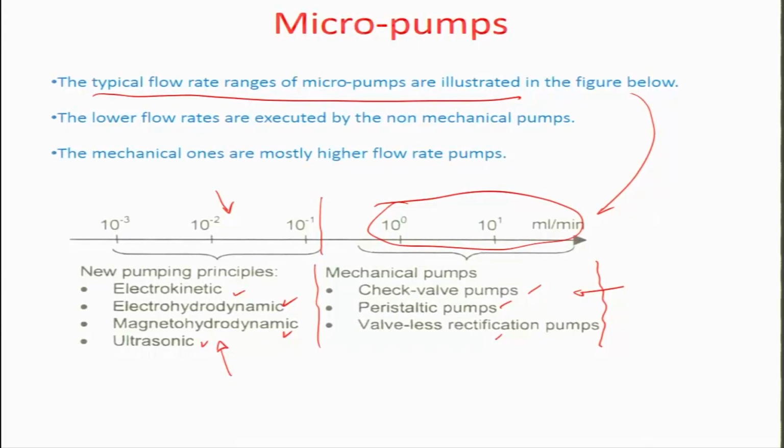But then what is the reason why such new pumping principles and such innovative actuation schemes are initiated? One of the major reasons is that in microfluidic flows, particularly when we are talking about applying these to human diagnostics, clinical diagnostics, etc., the volume is very low, and you have to have a very controlled motion of a very small amount of fluid within chip size platforms, so that they can have everything including signal transduction, the recognition of the element, the signal readability aspects, the interpretation aspects in a very small area.